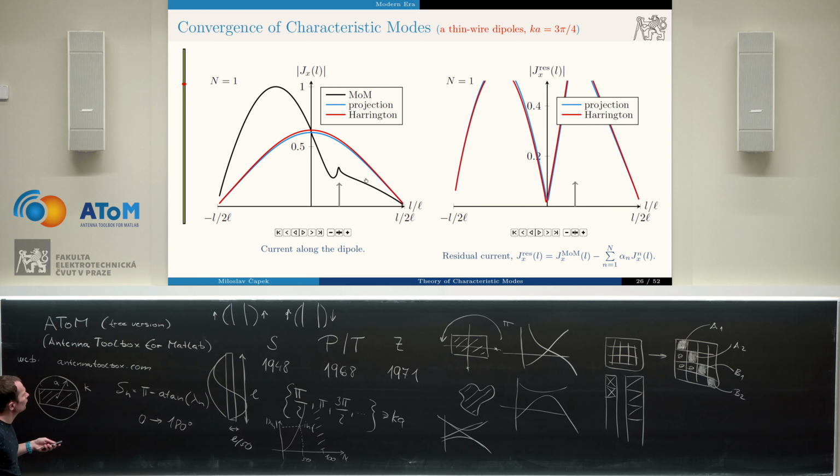And studies like this can be easily done, and the modal Q factors can be summed up together. With this procedure, you can extremely easily, for example, find the optimal placement for your feeders to get an antenna which has as low Q as possible. Okay, this can be done not only with Q, but it could be done with an arbitrary antenna metric.